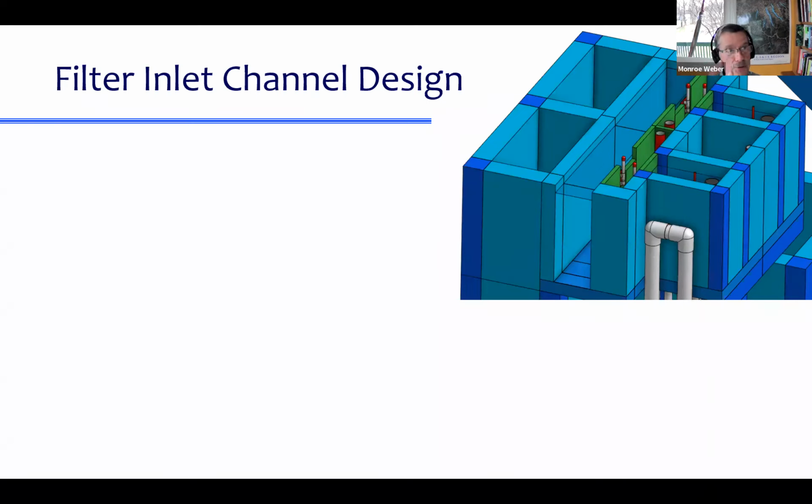And so we have to make the channel big so that the velocity in the channel is low. And we have to have a fair amount of head loss over these two weirs so that the change in water depth in the channel doesn't matter. Wow, with that, now that you've been shocked in realizing that the shortest path is not necessarily the way the water will choose to go, I will quit.